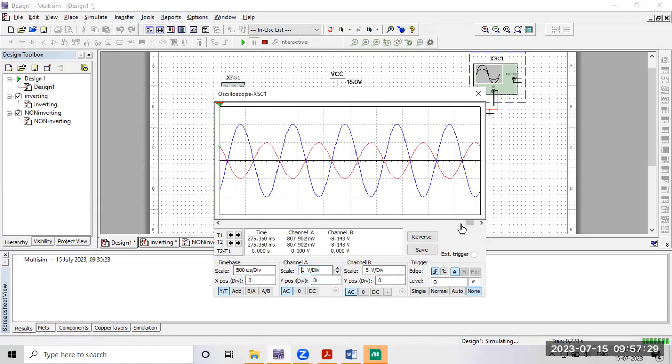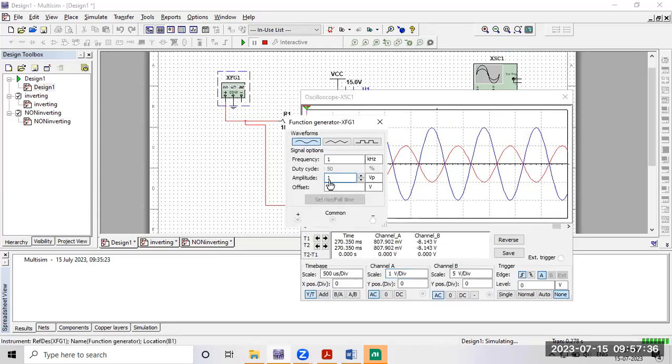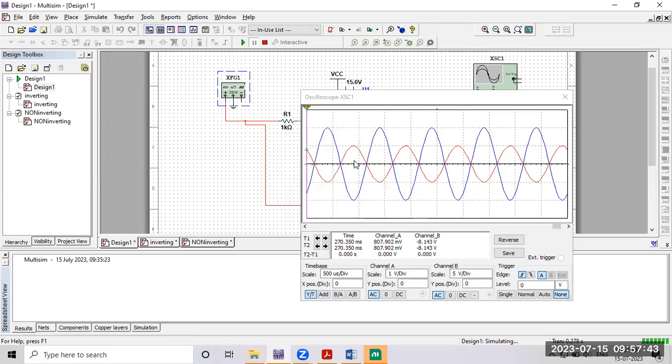Hold. Okay. Now you can measure what is the input voltage. Here you can observe signal generator 1. 1 is nothing but 2 volts peak to peak. 1 V peak, that is nothing but 2 peak to peak. Observe here: the red color waveform is nothing but the input waveform. The input waveform covers two boxes. Two boxes into 1 volt per division is nothing but 2 volts. Okay, 2 into 1, that is nothing but 2 volts peak to peak.